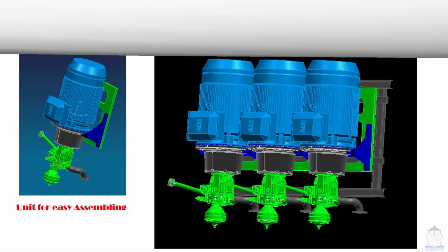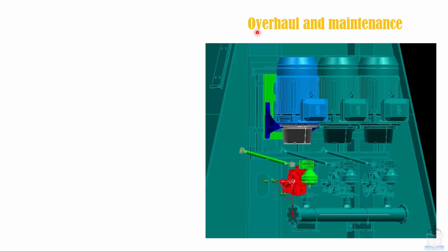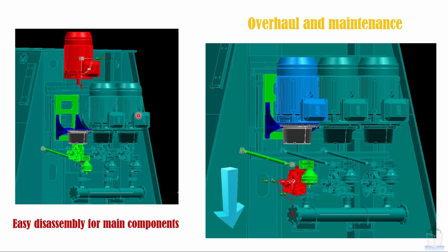Moving next, these pumps are also designed to facilitate easy dismantling and maintenance. For example, if you want to carry out any job on the pump part, then just remove some bolts and slide down the pump part and carry out any maintenance easily. In the same way, if you want to do any maintenance on the motor part, then just remove some screws and lift the motor part from its place.